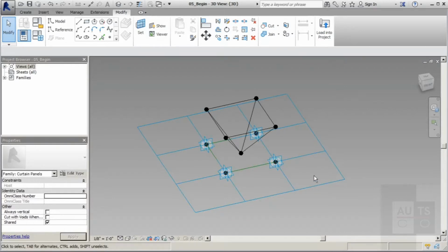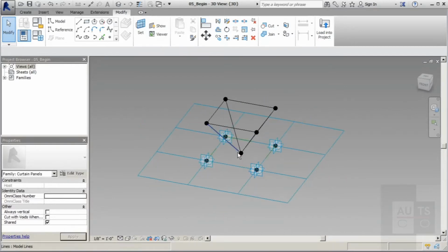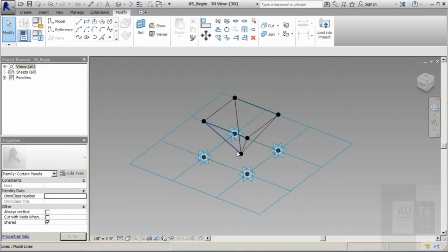So now what we can do is add some thickness to all of these pieces. My strategy is I want these struts to be a little bit thicker than what's going on at these edges, because these are going to be holding in glass mostly, and these are going to be supporting the weight of the glass as well as anything else that might be on that roof, maybe some wind loads or maybe some snow loads, but maybe our site doesn't have snow. Either way, this is holding up the glass and the frame. It's pretty heavy, so I'm going to make this a little bit thicker.